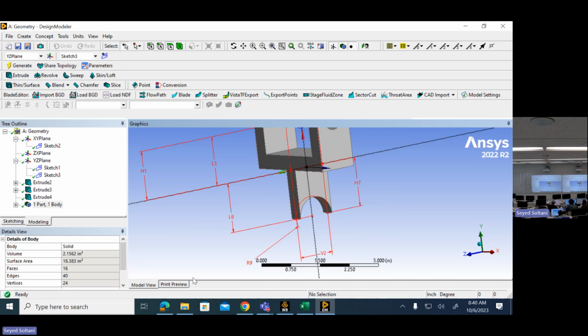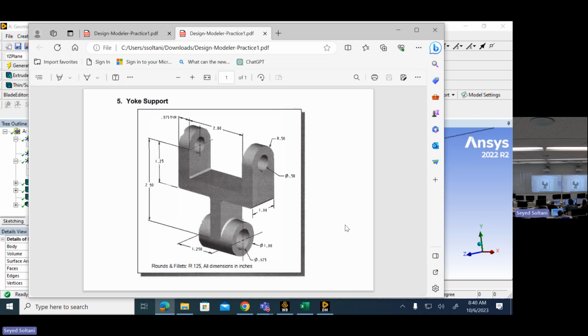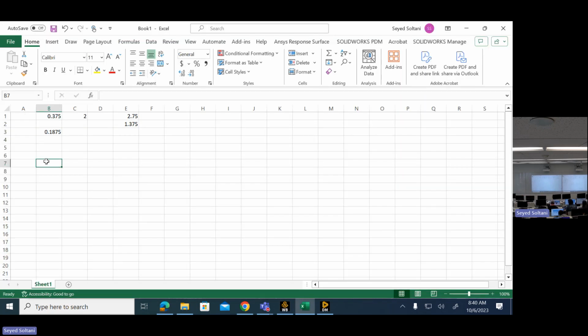All right, so I still need to go back to the drawing just to get the depth of extrusion. In this case, because I'm going to do a symmetric both sides, it will be half of this. To make sure I'm using the right numbers, I have to use this 1.5, and then the depth of extrusion that I'm going to use is 0.625.